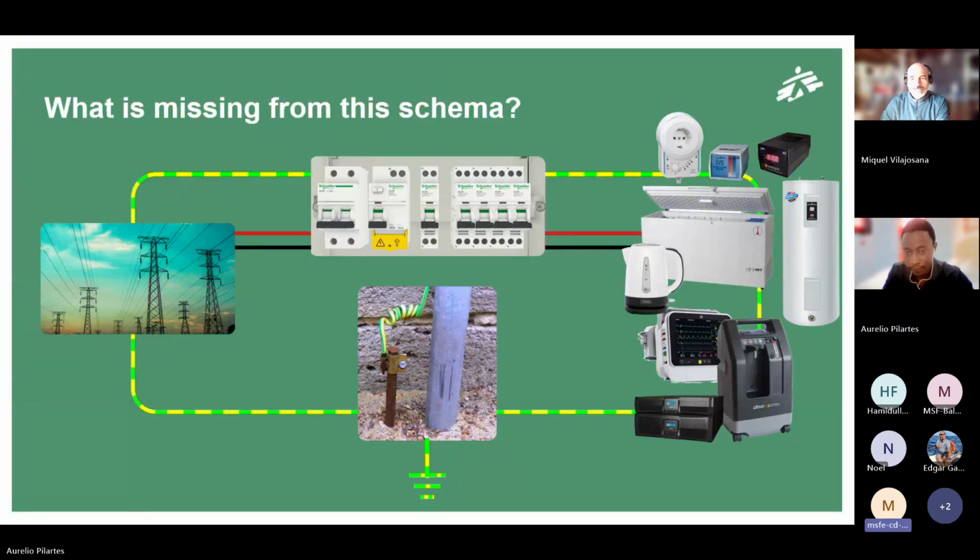The ground system, I think it is not properly installed here, because the cable, I think, is not the proper one, and the way of installation is not good. It was supposed to be inside of half. Yes, it's just an observation. Yes, good.